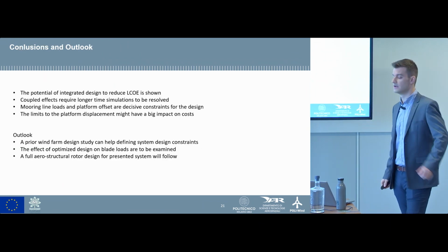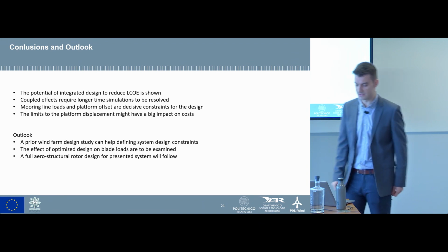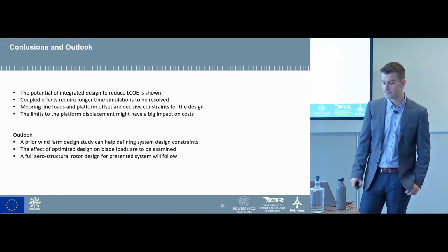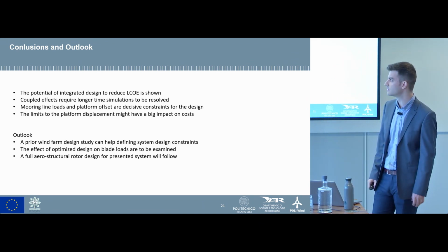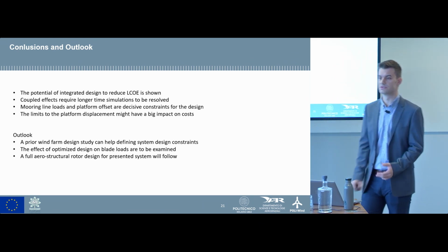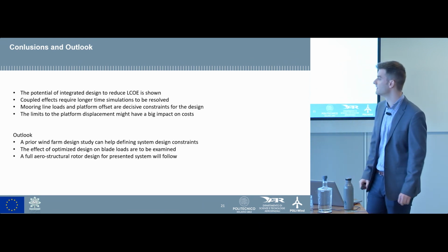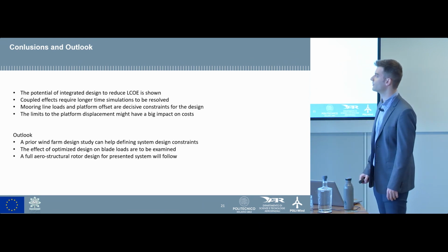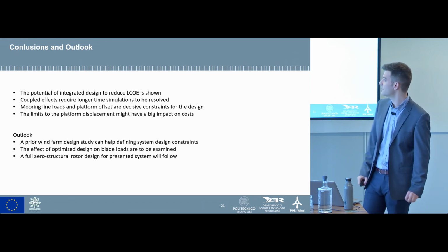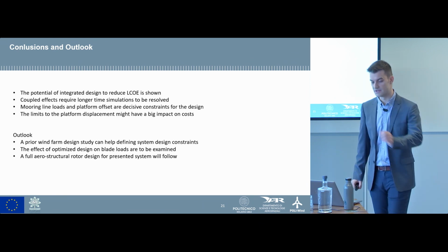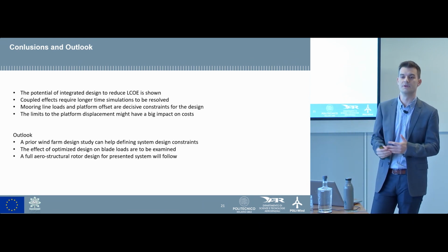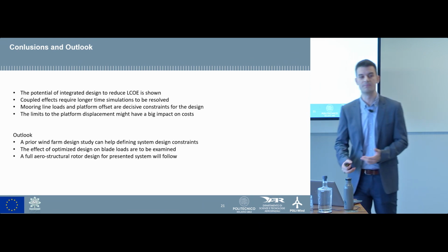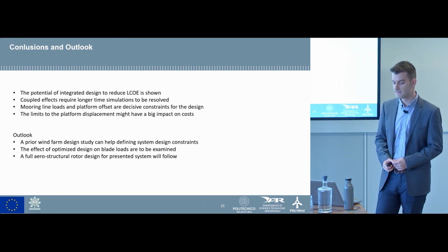And to conclude, we have shown the potential of the integrated design to reduce the LCOE. We have seen that the coupled effects require longer time simulations to be resolved. That's why this design procedure takes a bit of a long time. And the mooring line loads and platform offset are decisive constraints for the design. And the limits to the platform displacement, so the maximum pitch and maximum horizontal offset of the platform, are going to have a huge impact on the costs.